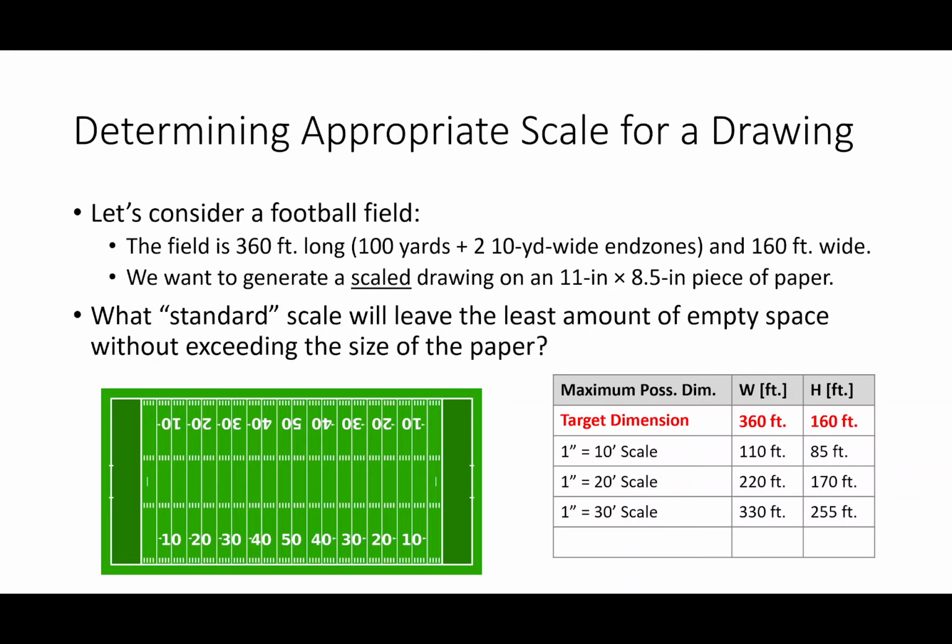The football field is 360 feet long, and 330 feet is the maximum I could do. So what about a 1 inch equals 40 foot scale? Could I do that? Yes, I could. Okay. So I propose that if you're going to print a football field on an 8.5 by 11 sheet of paper, do it at a 1 inch equals 40 foot scale. Does that idea kind of make sense?